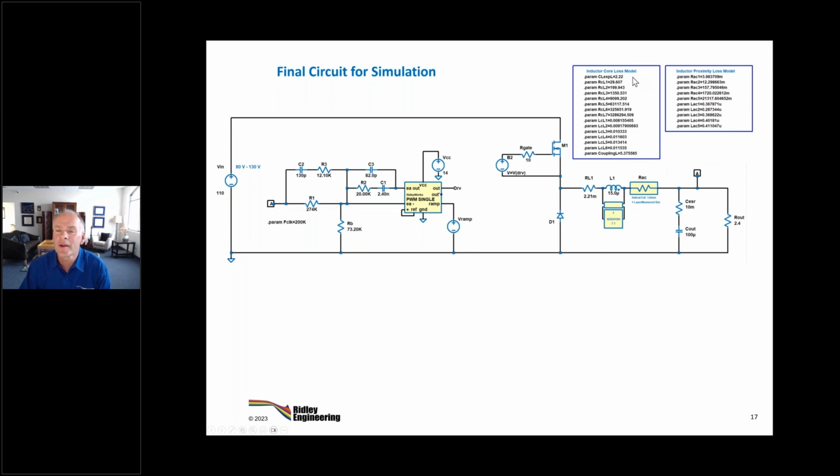Inductor core loss model, we have a 6th order model for the core loss that we needed. Again, 6 elements here, 6 elements here. There's a non-linear element here representing the delta P to something more than delta P squared. So that all goes in. Everything here is generated automatically. Trust me, if you have to generate these models by hand, some of you might want to do this yourself, and you have to type it into LTspice when you get over there, you're going to do it once and then you're going to stop because it's too hard. So automating this is a big, big step for us.